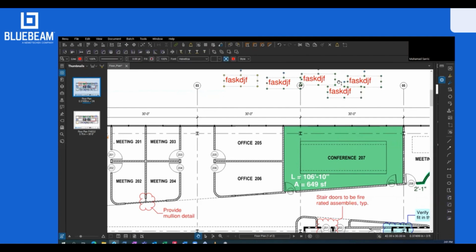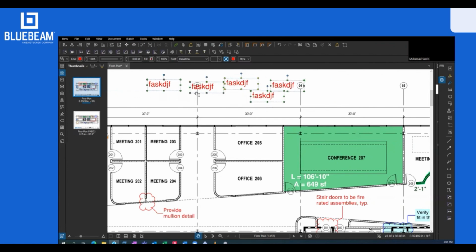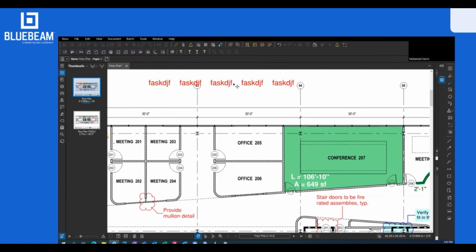And you can do bulk actions. So up here in the top left, you have these alignment tools that you can utilize. If I want to align all the middles together, boom, they're all aligned. And then say I want to space them out evenly, I can use this distribute horizontally. And now you see they all pretty much have the spacing right.